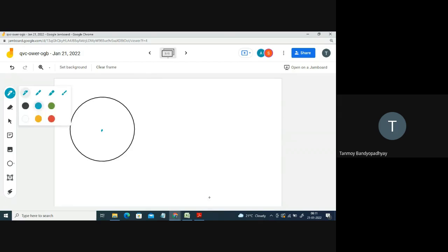In that case, if you take B, let's see what happens. At this point you are having RB. This is the point B, and you will be having a frictional force FB. It is not slipping, so since it is not slipping, there is a frictional force actually. So you have to take FB also into account. At this point this is the reaction force; since it is resting on another sphere, this is RA.